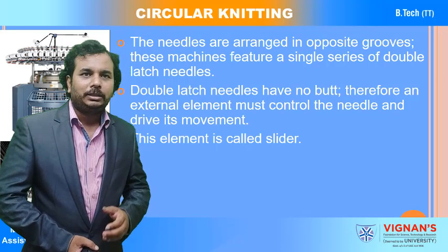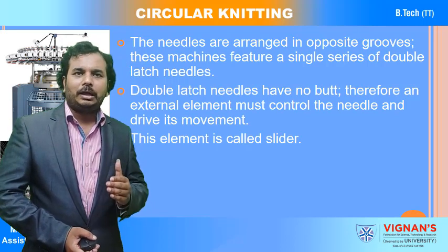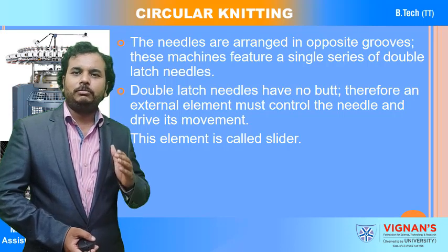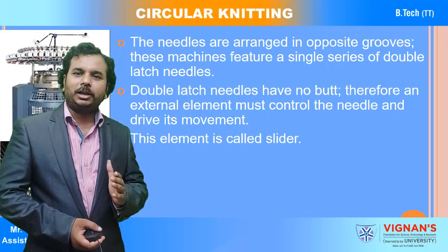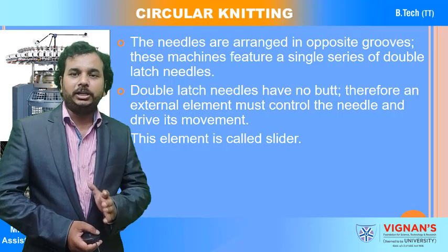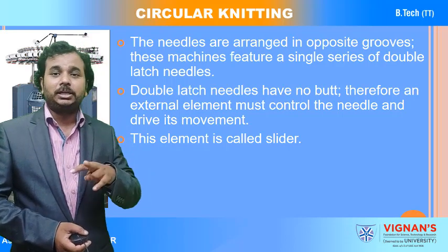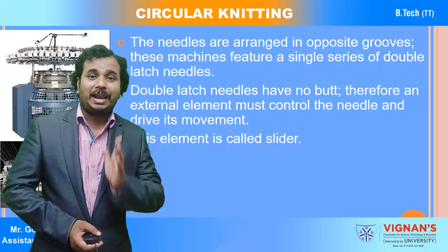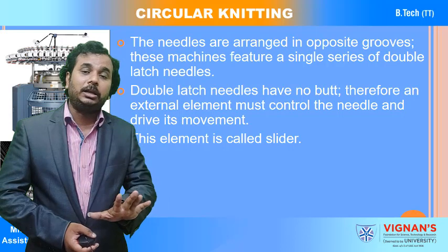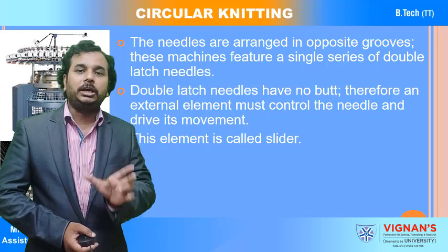Now, the double latch needles have no butts. You need to remember that in the double cylinder category we use double latch needles, with a latch on both sides of the needle. There is no butt in the needle.